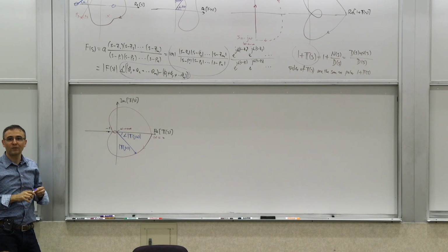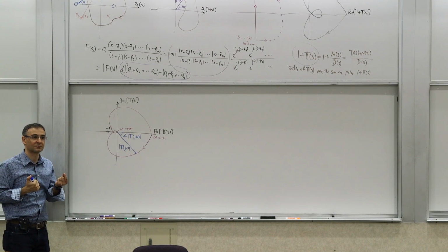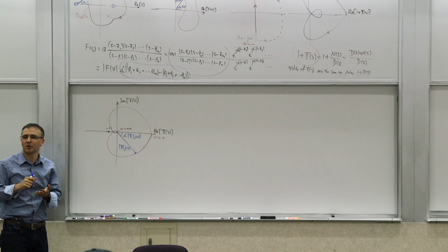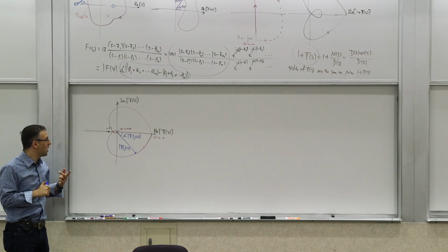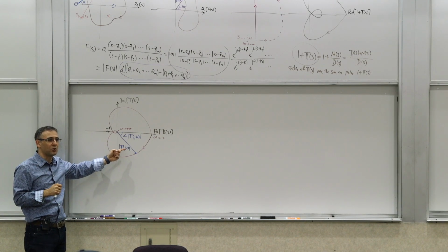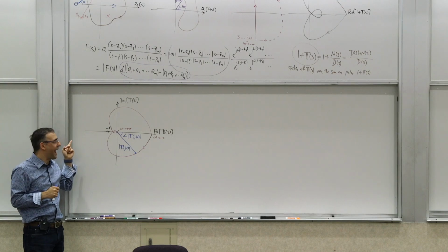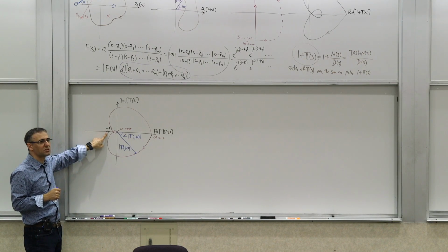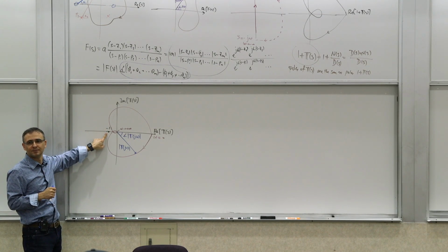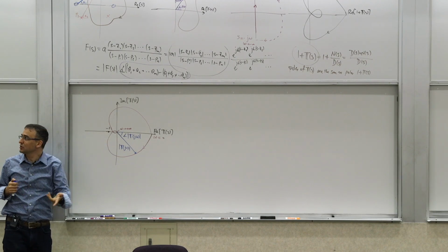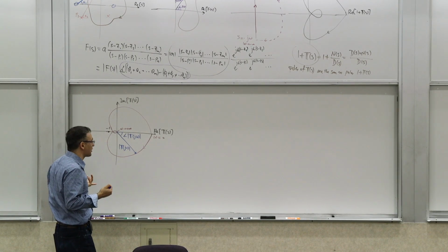Right? So if you have the Bode plot somehow, either through a measurement or calculation or something like that, you just take the Bode plot and do a polar plot of the Bode plot. And you look at how it behaves with respect to point -1. And that gives you a sense of whether or not you're stable.